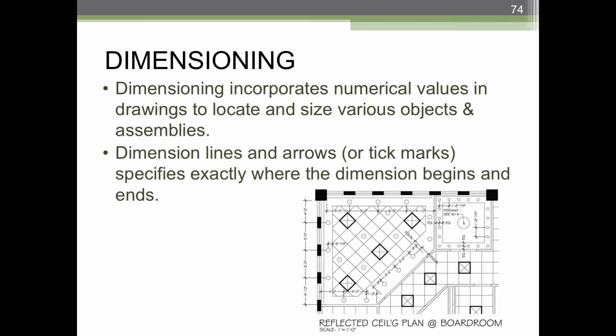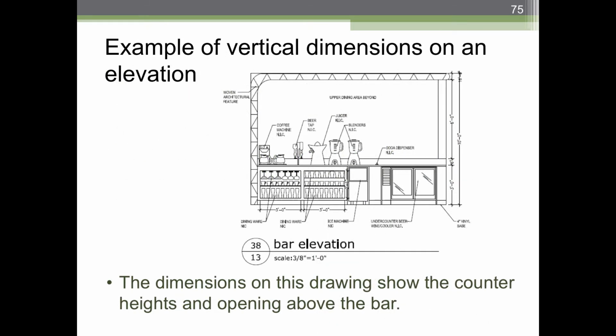Anyway, another thing that you typically do in floor plans is dimensioning. And dimensioning is kind of this relentless thing that you might say, why do I even need to bother? Can't they just look on the drawings? I mean, on the electronic document? Well, first of all, they can't because you don't usually give them the electronic documents. And second of all, you don't want them measuring off of a printed drawing. Because drawings are never printed exactly right.